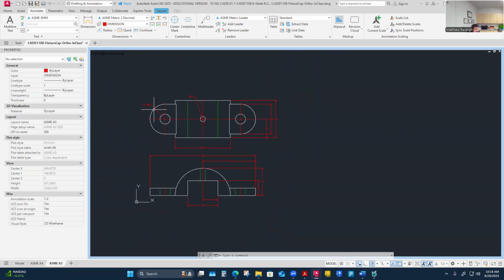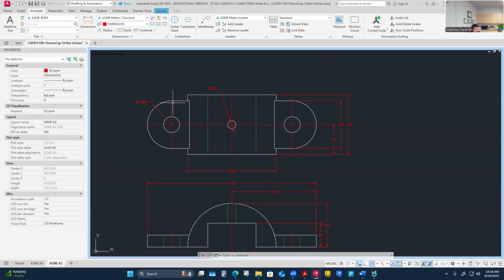I've got a radius now. Maybe that's a little bit redundant because I could say this is the radius. Well, that would be the diameter, but I think these worked well together to put them both on there. It's not truly redundant because it's not the exact same dimension, but a person could figure out what the diameter is with that. Here I've done the math for them already. And really I'm actually going to do that width, and then I'm also going to give it a location.